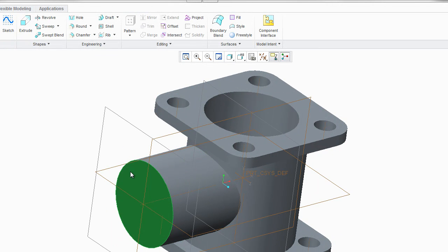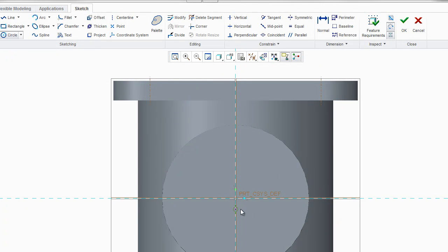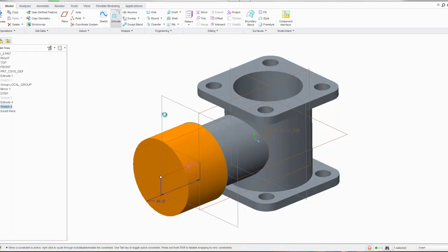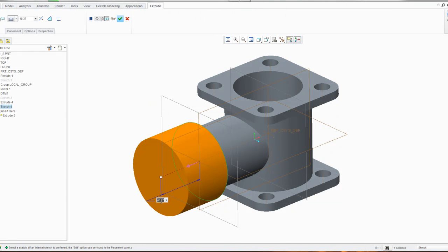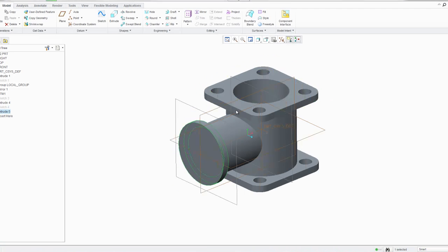And let's go ahead and add our next to the last feature. Create a sketch, reorient to sketch view, and I'll use the circle. Define a diameter of 75. Check out of my dashboard. Extrude to set a thickness of 5. Now let's do 8. Alright. Okay, so we're almost done.